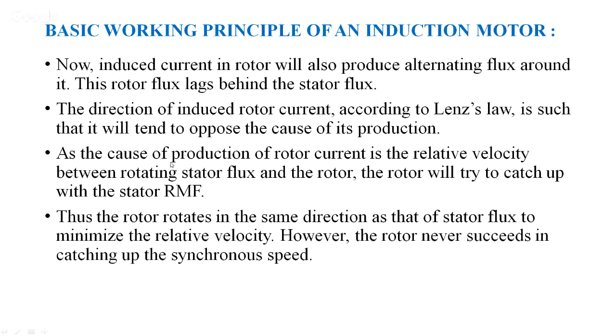As the cause of production of the rotor current is the relative velocity between the rotating stator flux and the rotor, the rotor will try to catch up with the stator rotating magnetic field. So, the stator rotating magnetic field is ahead of the rotor flux. That means the rotor flux is always lagging behind the stator flux.